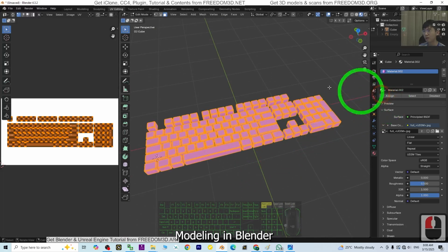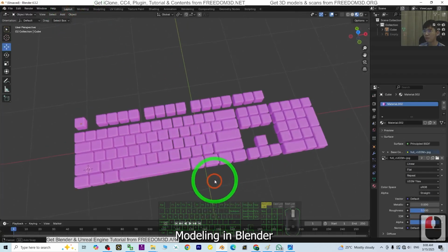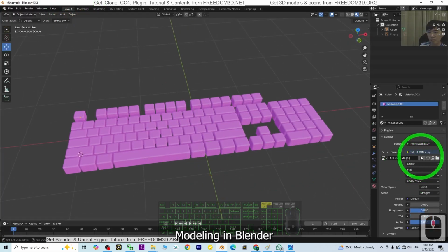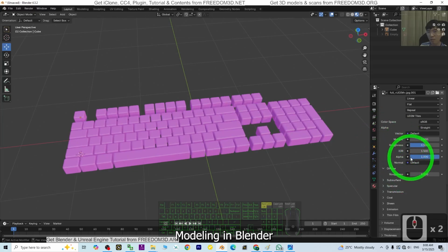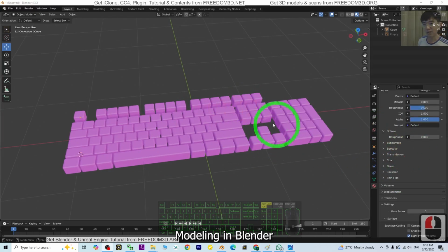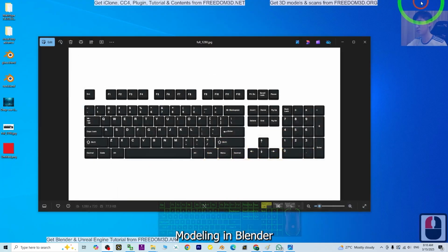So we assign it. So if you see something like this, the texture cannot be attached. Go to the UV editing, this still failed. That means this picture has some problem. We are going to just convert the picture's format. Alright, the picture is at here.